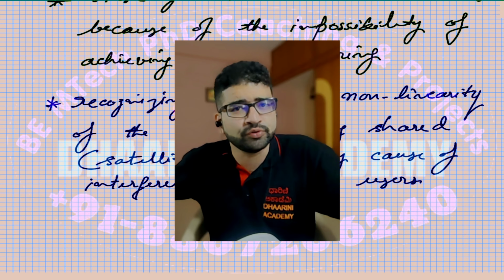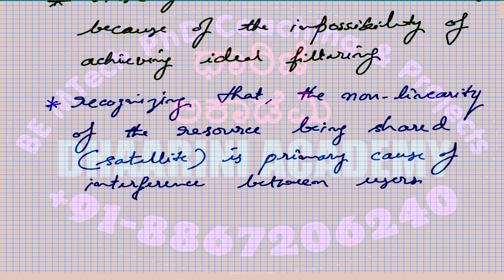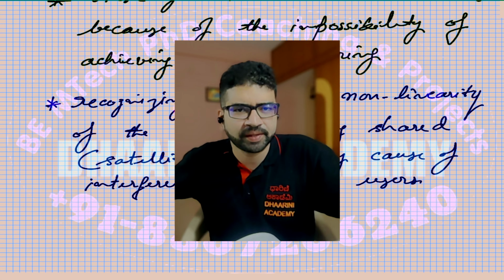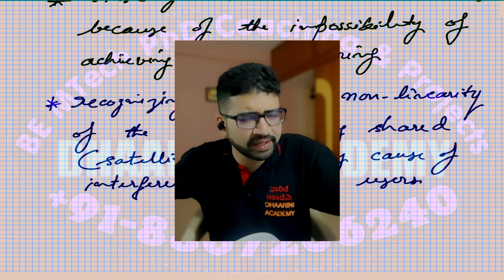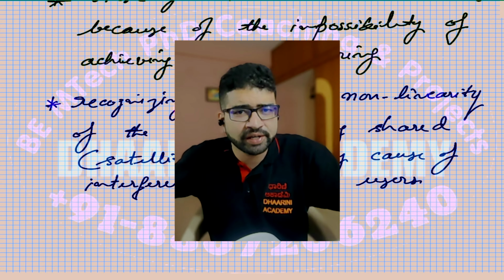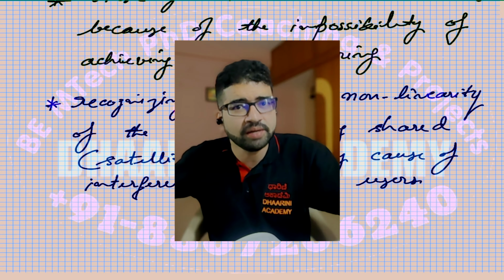So what do you do? How do you reduce this? You are going to make sure that the amplifiers or any other sort of circuits, maybe filters, within that shared resource are being operated below their complete capacity. You are not going to use it to the full extent, right? You don't give the full voltage as input, you try to give a lesser voltage, so that at least you reduce some interference because of that device.